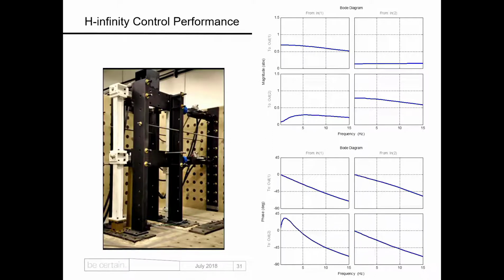You push one of them, the other gets retracted, and push the other one, the first one gets retracted. And then using the H-infinity loop shaping, it can minimize those couplings. And then this one is also closer to 1, right? The diagonal term is also close to 1.